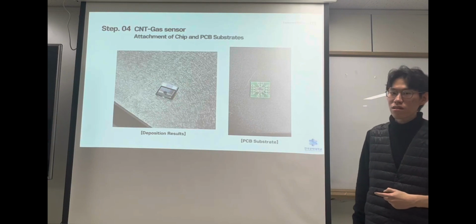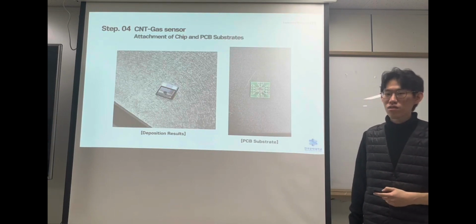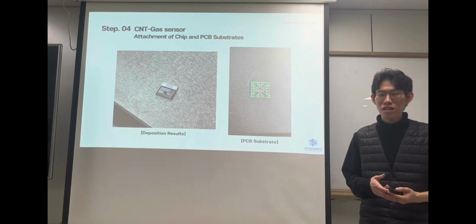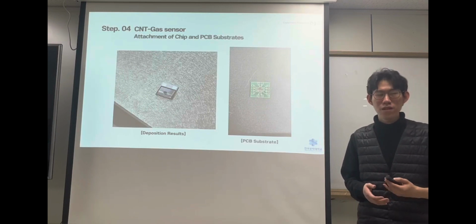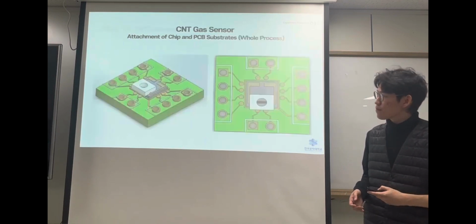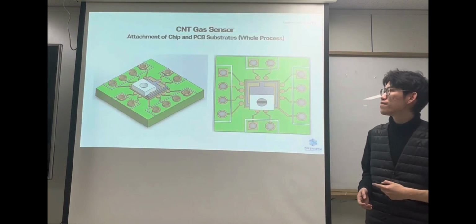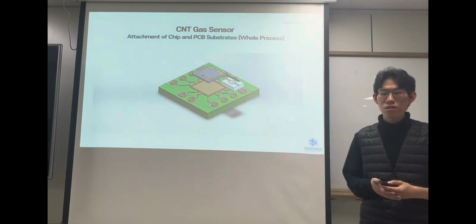This figure is the result of our deposition, and the unit is now ready to be attached to a PCB substrate. With silver paste and wire bonding, we will create a sensor and test the sensor's performance in different conditions. This is an example of our completed sensor. And we have also prepared a short assembly video.